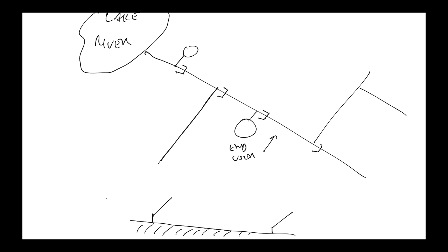And the job of the control system is to make adjustments to the positions of those regulating structures in order to maintain the water levels just upstream of those structures at set points that are consistent with the expected flow demand. So the flow of water throughout the network is entirely powered by gravity. So flow is in this direction. Flows from upstream to downstream.